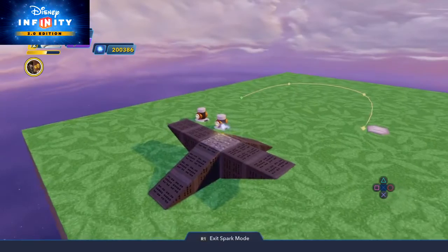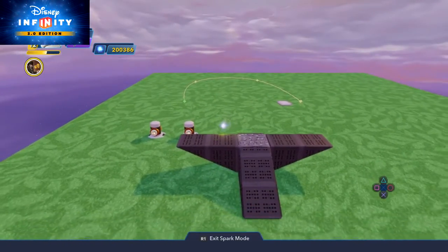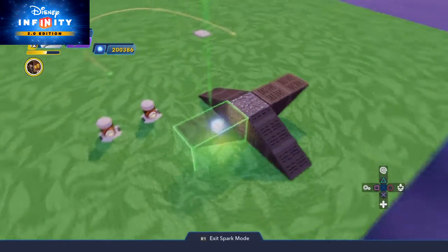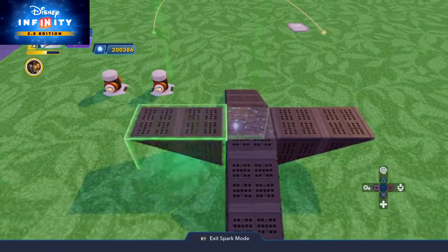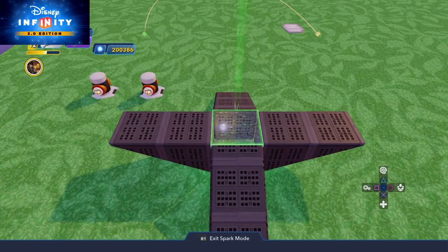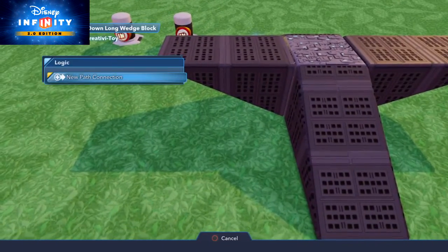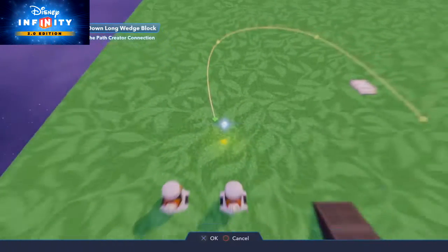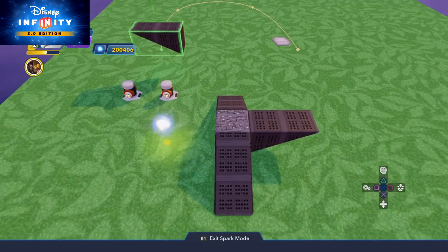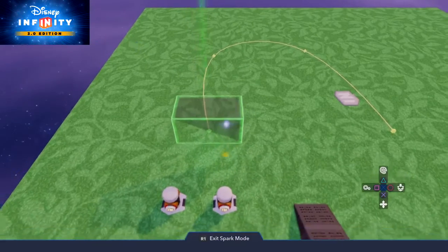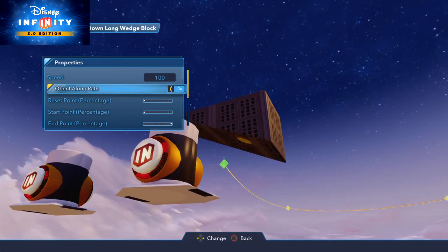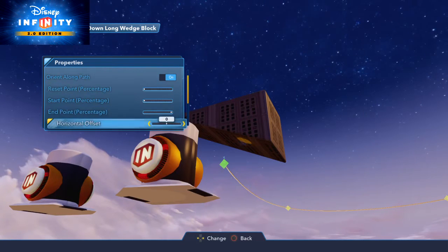Now we're going to start putting this structure onto that spline tool, and just let me say, use some graph paper to draw it out first sometimes if it's something complicated. But the center piece, this is the center piece, it's what I want centered on that spline. Put it on last, just to make everything so much simpler for yourself. So I'm going to put that piece on the side, and compared to the centerpiece, it was left of the centerpiece. So we're going to go into this piece, and always, always, always, when you're doing blocks, orient along path. It just makes everything a million times easier.